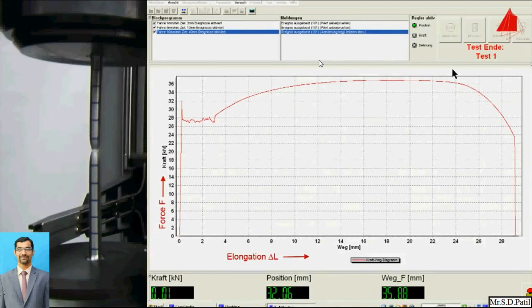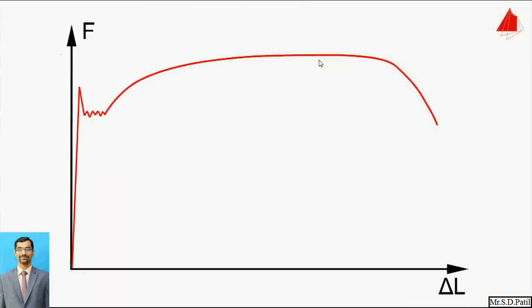Here we can see the maximum force. Here it will reach 34, and the deflection. So this will be the position, this will be the force in the elastic phase. So to calculate the yield force, and then this will be the maximum force to achieve the ultimate tensile strength of that particular component. So this will be the stress sigma.